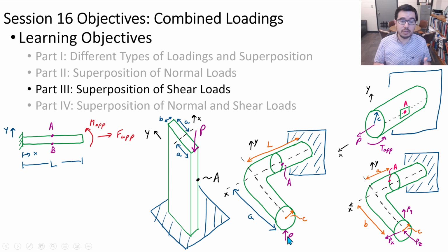the force itself is not a torque, but it's applying a torque to a system, or it's creating an internal shear force to the system that results in a shear stress, which is actually what's happening here. We have an average shear stress that results in a transverse shear stress, and we also have a torsional or torque that's being induced onto this shaft that's causing a shear stress.